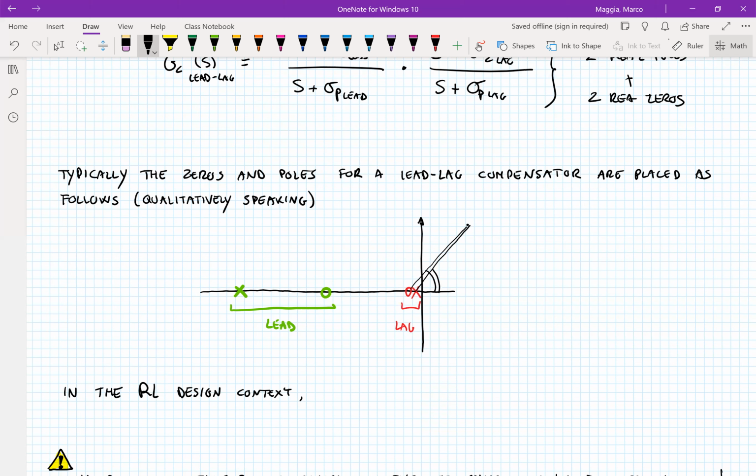On the other hand, the lead compensator introduces two angles that are quite different when it comes to the pole and the zero. Therefore, the lead compensator will substantially change the root locus of the uncompensated system. And that's exactly why we use the lead compensator part.